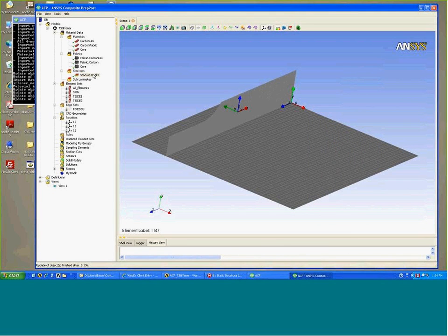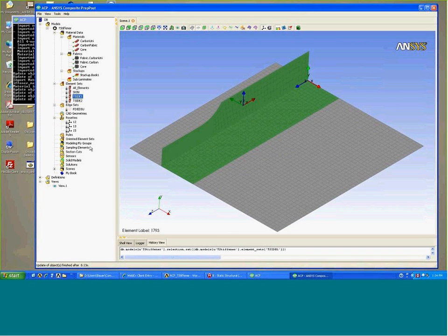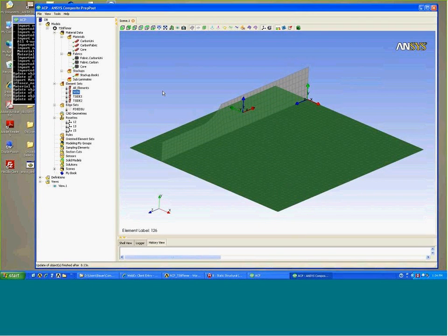You'll see that in our stacking sequence, when we create our ply groups, we can use both fabrics and stackups to combine to build our final laminate. Next, let's take a look at what's next in our outline tree, element sets. These sets are groups of elements, essentially regions where we will apply our ply groups. These element sets come in from either Mechanical or Mechanical APDL as named selections or named components.